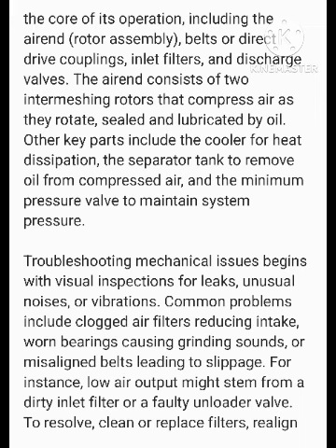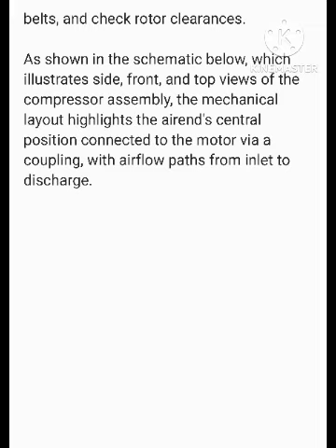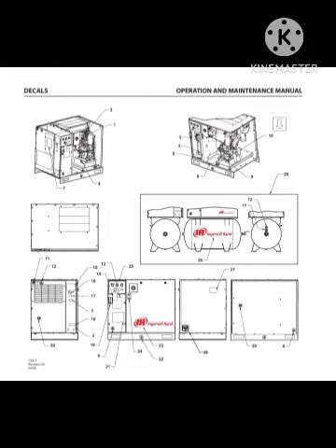For instance, low air output might stem from a dirty inlet filter or a faulty unloader valve. To resolve, clean or replace filters, realign belts, and check rotor clearances. As shown in the schematic below, which illustrates side, front, and top views of the compressor assembly, the mechanical layout highlights the air end's central position connected to the motor via a coupling, with airflow paths from inlet to discharge.